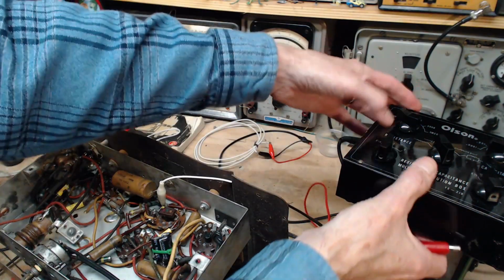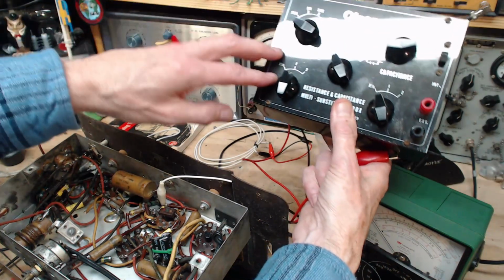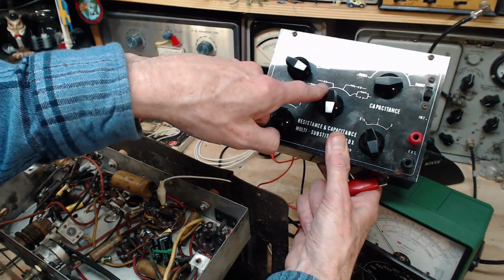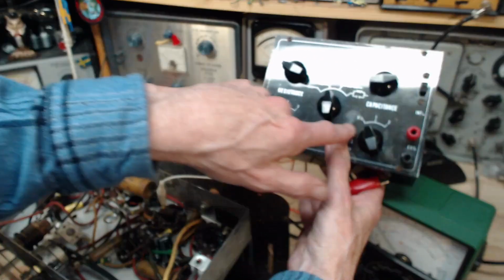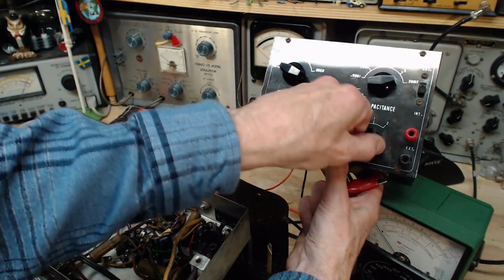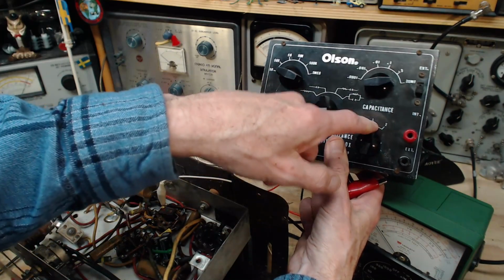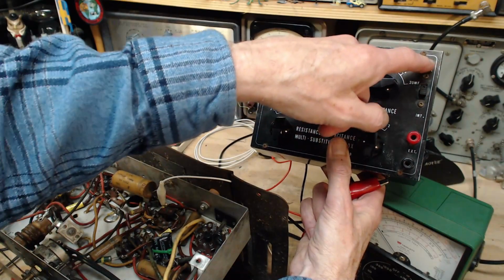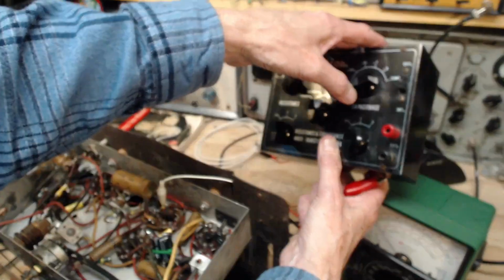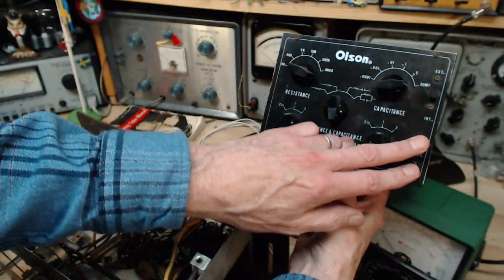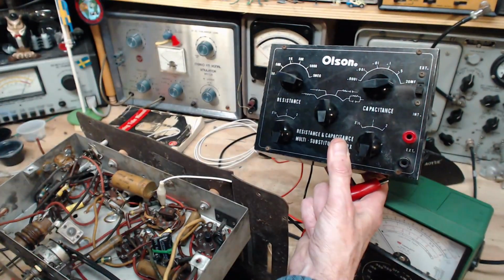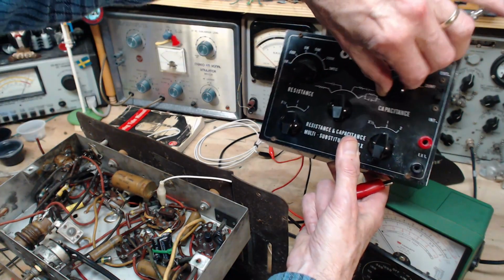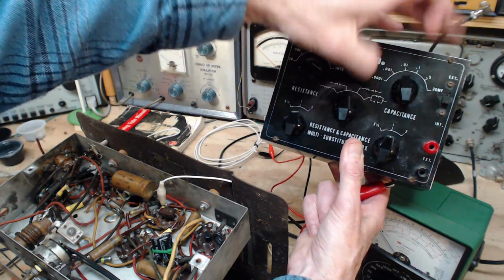Let's just check the settings there, Jim, before you do that. We're going to want to use the capacitor only setting to start with anyway. And we have capacitor half, 1, or double. We're going to go to 1. And external, internal, what is that? External. So we'll leave it on internal. Offhand, I think this is good. And we're going to want not to have this up at 20 microfarad. We'll start with 0.01.